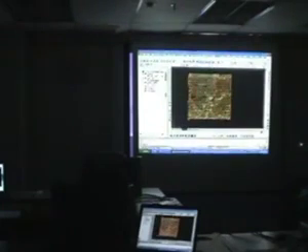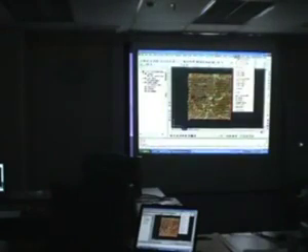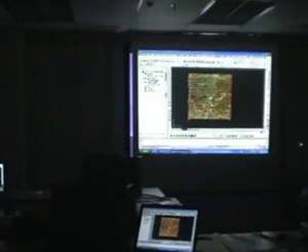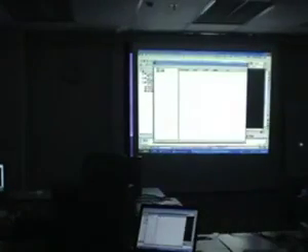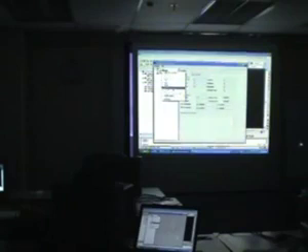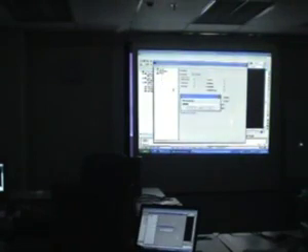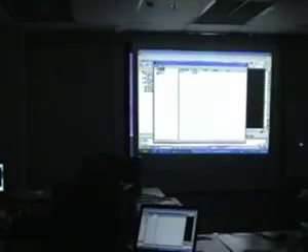So now we've got our points, and I'm going to run the triangulation now so you can see this in 3D. I'm going to go to Terrain, go to Terrain Model Explorer, and I'm going to create a new surface. Each surface is basically like a new level, for example. Let's say I call this OGL, original ground level. So this indicates this is going to be the original level, the existing surface which the project looks like.